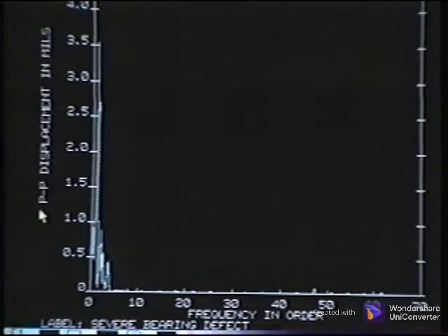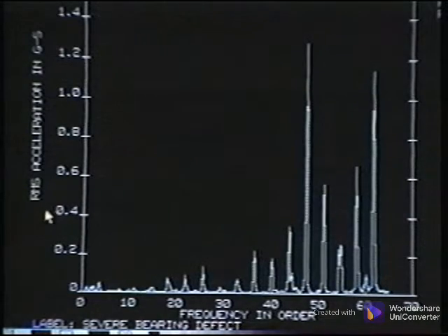When this same spectrum is displayed in displacement, all the high-frequency energy disappears. It may seem as if the machine is healed, but no mechanical change has occurred. Displacement amplifies the low-frequency energy and minimizes the higher frequencies. Displaying the same spectrum in acceleration now amplifies the high frequencies and minimizes the lower frequencies. This can cause you to